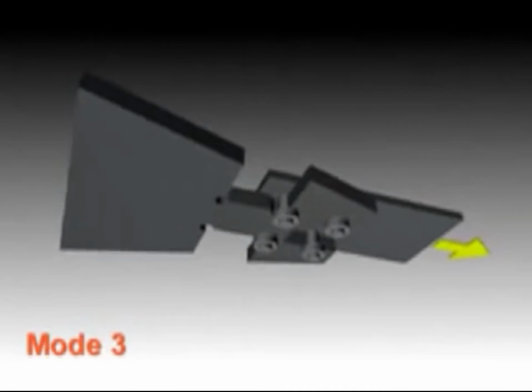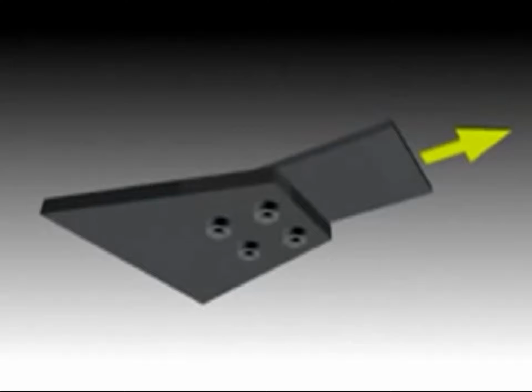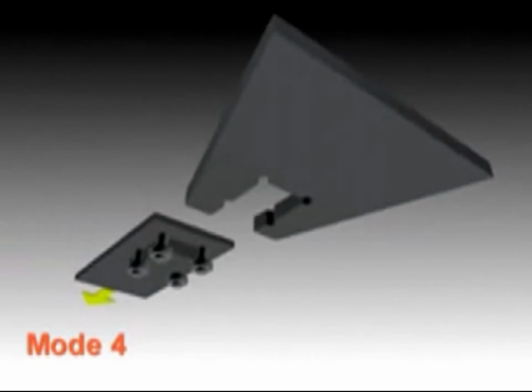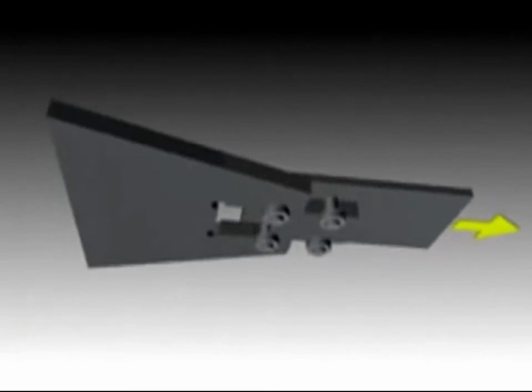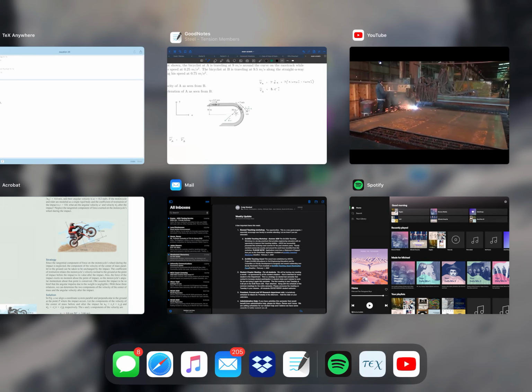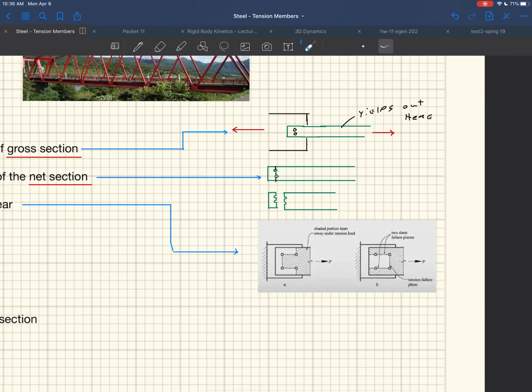In this case, it's the plate that failed and not the member that's attached to it. So really, in this particular case, there'd be 4 different mechanisms that you would have to look at, right? Because now you could also fail like that, where it rips off the middle part of the plate that it's attached to. And so you'd have all of those limit states that you would have to calculate. That's how you know what that looks like. Specialty flat plate pieces, such as stiffener plates, column caps.